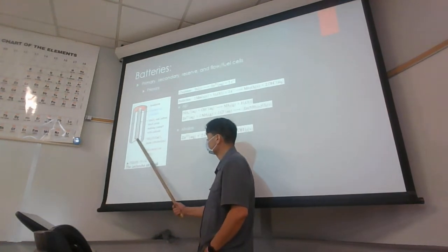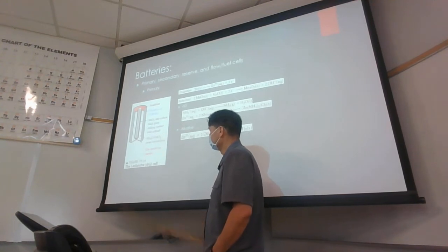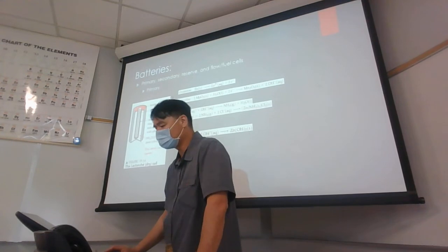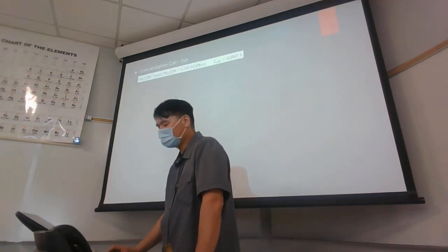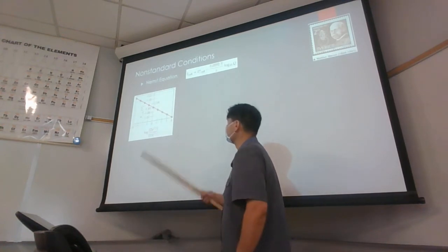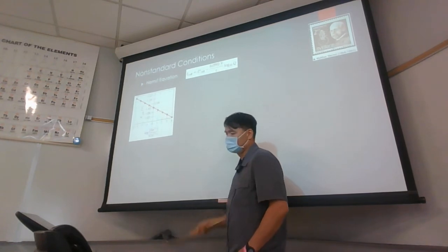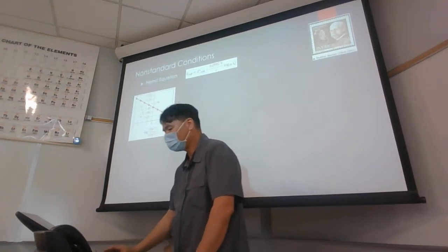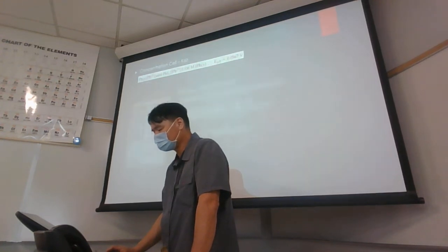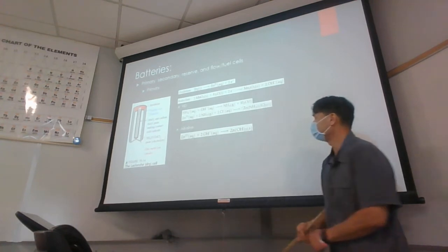And so one of the tricks to getting stable voltage in a battery is by using as many solids and liquids as possible. And that's what's done here, because if the voltage starts dropping off immediately, then the battery becomes pretty useless quite quickly, if the voltage would drop off like this, according to the Nernst equation. And a lot of electronic devices require a certain minimum voltage to operate. So, this is the regular heavy-duty battery.